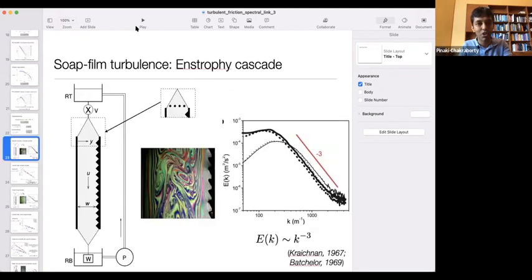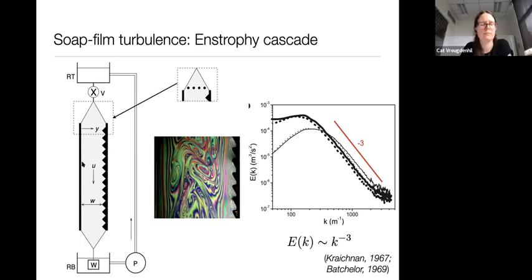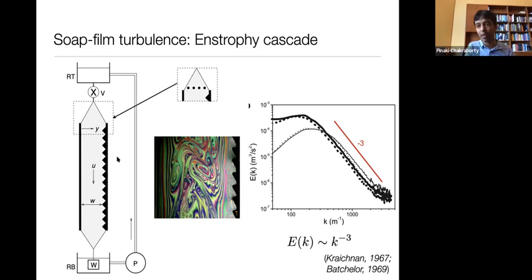So let's see how we actually measure the friction. To do it with the smooth pipe, the smooth channel, we can have one wall smooth, or in fact both walls smooth, and we have done both, the results are the same if we just focus on the smooth side. What we do is we shine LDV laser beams at different points across the width of the pipe. This LDV is on a translation stage, and you just measure the velocity time series here, here, here, and so on and so forth. And you can measure the whole velocity profile across the whole width of the channel. And if it's a 2-component LDV, you can also measure the Reynolds stress profile.